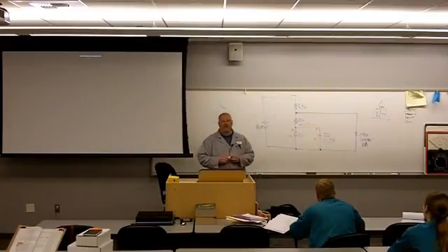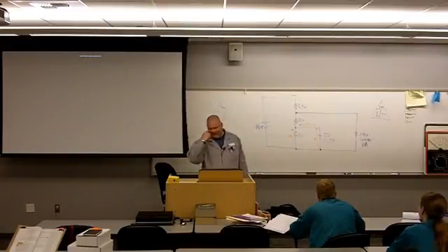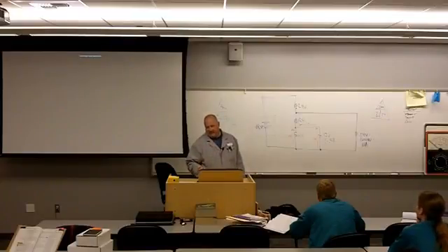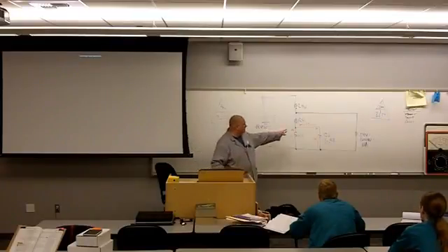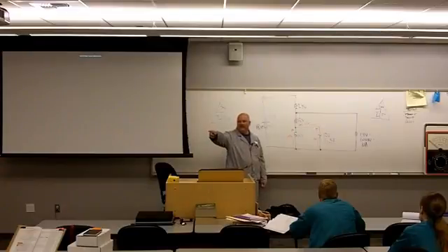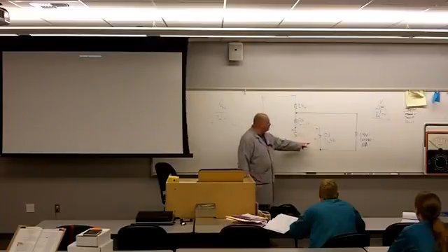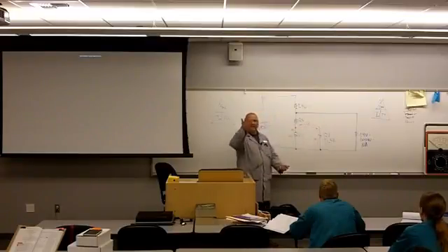But again, what's going to bring tears to my eyes is if you quote me laws. Are there any laws that govern what's happening here in this node? Absolutely. Kirchhoff's law. I've got 1.05 coming up here. I've got 0.5 here. We've got a traffic cop standing in the middle of that intersection. How much current is driving away from him?